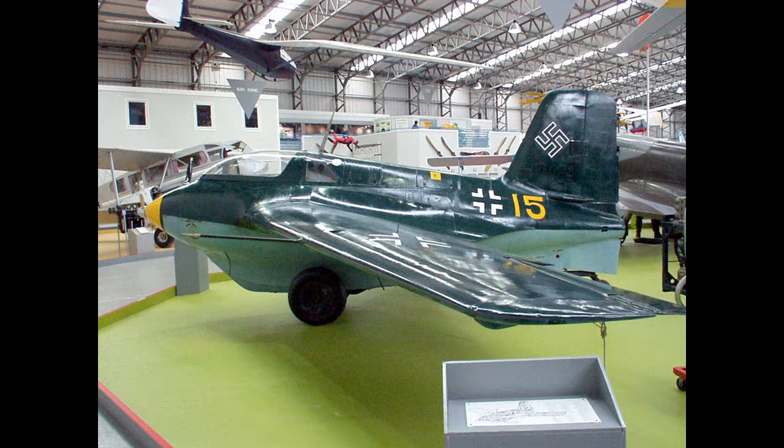A rocket engine has many of the same advantages of a jet engine. There are no propeller tip speeds to be concerned about, no P-factor or other asymmetrical thrust issues from a single engine, and its thrust and power vary with speed in the same way as a jet. These are all huge advantages over piston engines. As compared to a jet, the rocket has a further advantage in that its thrust does not decrease with altitude.